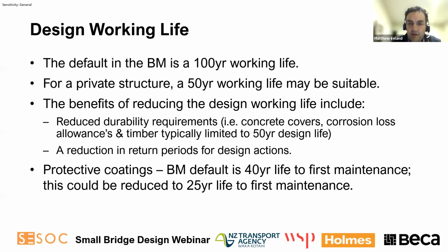That could be concrete covers, corrosion loss allowance for uncoated steel elements, and also if your structure's using timber, because within the New Zealand standards, timber durability is only really covered up to a 50-year design life at the moment. So it just makes it a bit easier to fit within those standards. Another benefit of reducing the design working life is a reduction in the return periods for design actions. I'm just going to cover that in a bit more detail on the next slide.